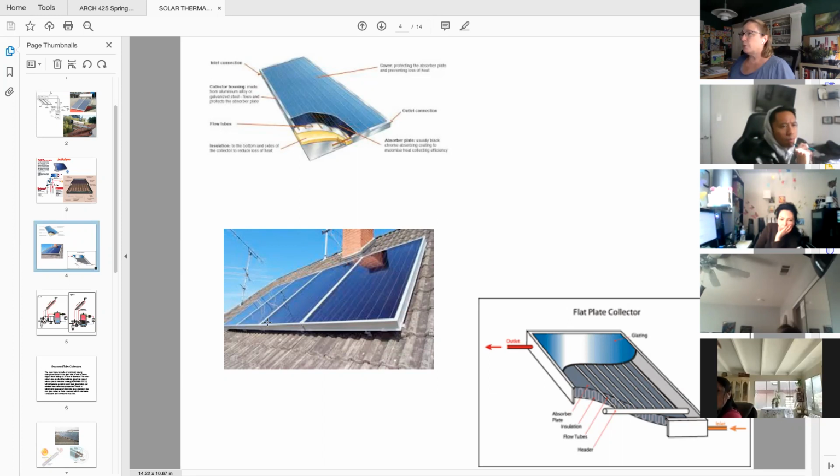And so if you're looking for energy efficiency improvement, adding in that solar thermal component skyrockets you. It also significantly helps contribute to your rating in your Title 24 compliance documents. You get a lot of bonus points for solar hot water.